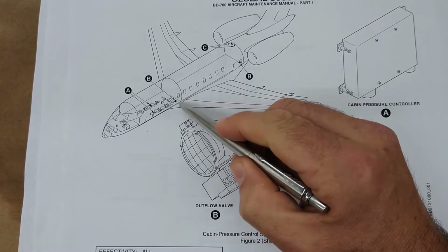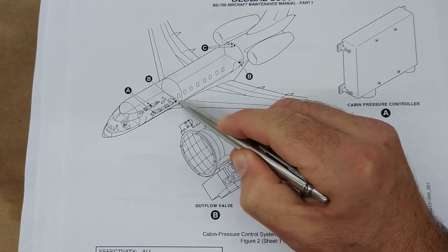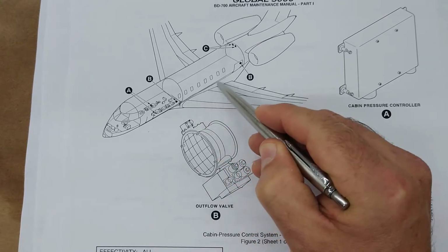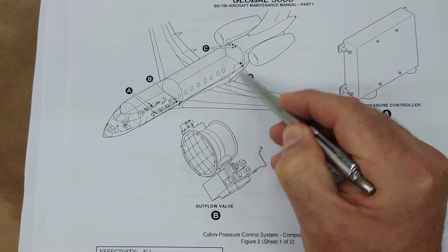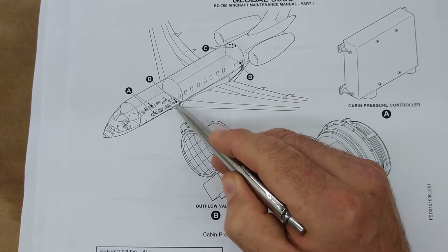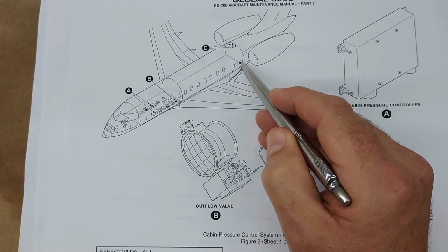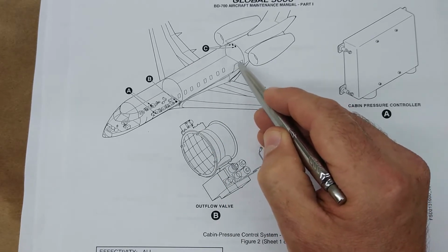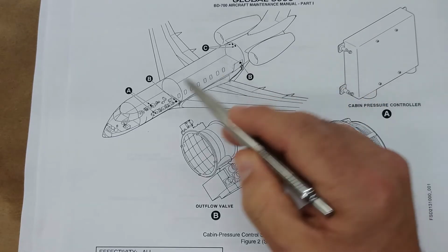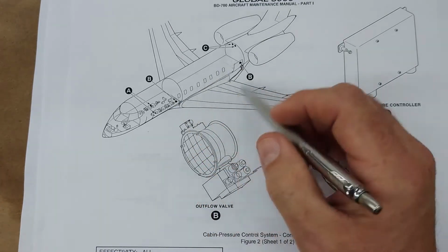So here we have the end of the floor of the pressurized compartment, and then it goes up and over the wing, and then it drops back down again below the cargo compartment back here. So this is one outflow valve, and I'll show you that. The second outflow valve is back here below the cargo compartment in this particular aircraft. And again, we'll go to the airplane in a little bit, and I'll show you those.